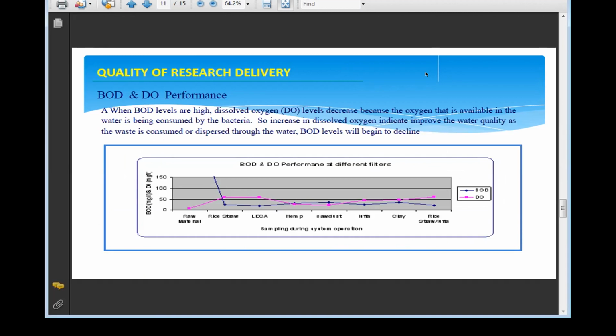and the requirement also lets us see the relation between BOD and DO, dissolved oxygen, which is very good. When the BOD is high, it means the oxygen is low. There is a reverse relation between both of them, which gives us the final result that the BOD, which is very important and a concern for the people working in the trickling system, is low.